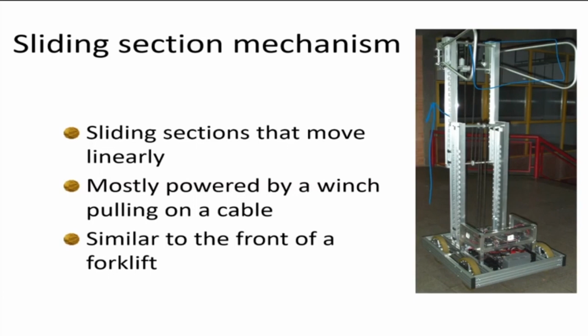Okay, so these are some of the examples that we need to keep in mind when we are designing a robotic system, because we start off with degrees of freedom, then we see other parameters that are required like structural index, then we see whether it is well conditioned, then we saw whether the inverse kinematic solution is possible in terms of the wrist design. And then finally, to apply the robot in an application, we need to see the kind of gripper that we are going to put on it. And today we looked at different grippers, right from industrial grippers to magnetic grippers to vacuum grippers.